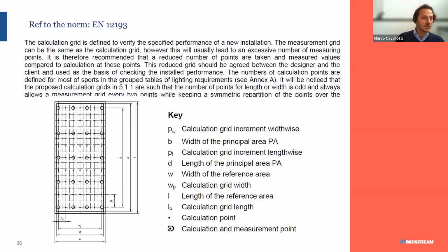If you have a procedure and you have a guide and you know how to do it, you can do it internally with your maintenance or the operational people. And of course, you don't have to do all the stands in the same night. You can do stands 1 to 5 in the first week, and then 5 to 10, and then keep rolling the checks within the year. So I don't know if you want to add anything else, Yuli, on this. No, that's it.